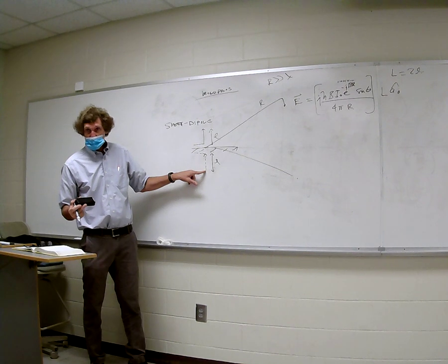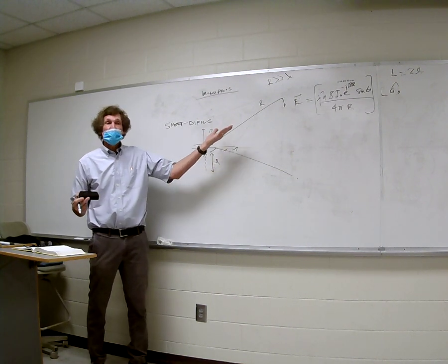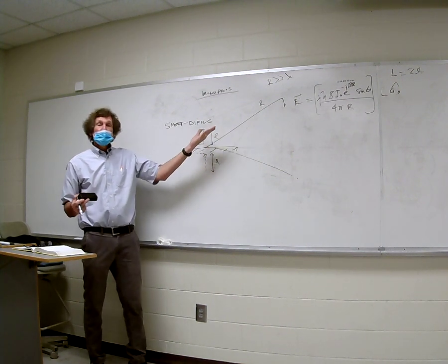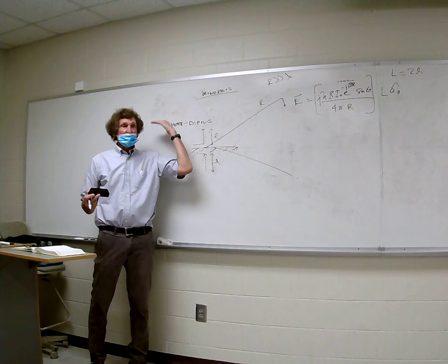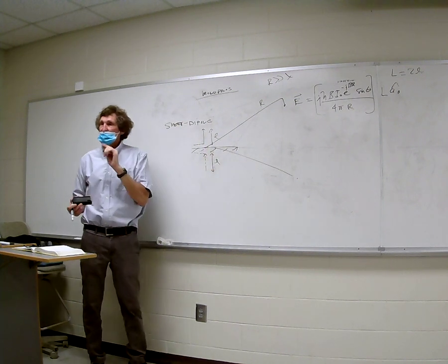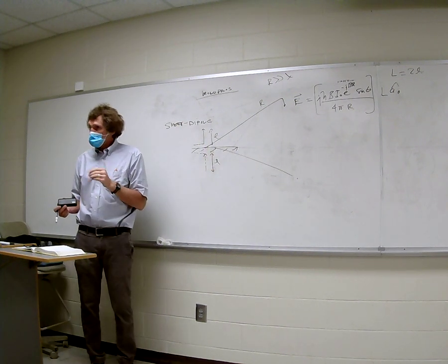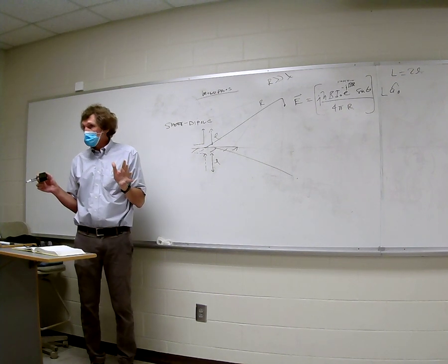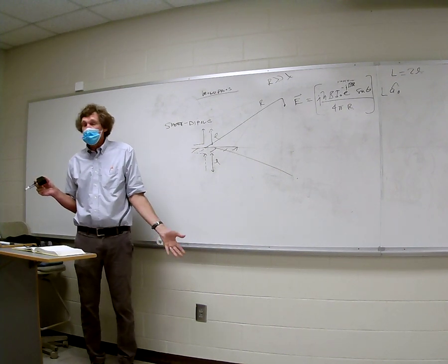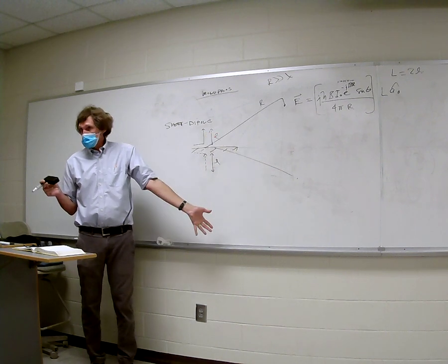The electric field from a half-wave dipole will be the same for a monopole of a quarter wavelength. But the power radiated is only radiated over the upper half. It's exactly 1/2 of the total power radiated by a dipole of equivalent length. Does that make sense to everybody? I can't radiate under the conductor. Follow me?